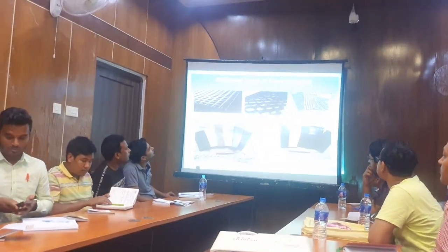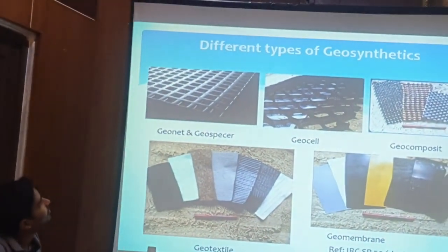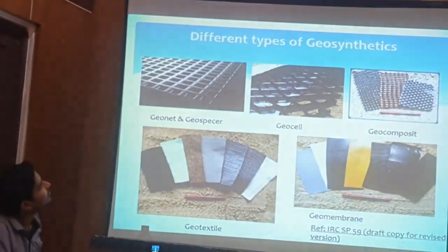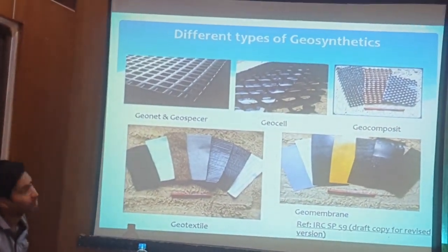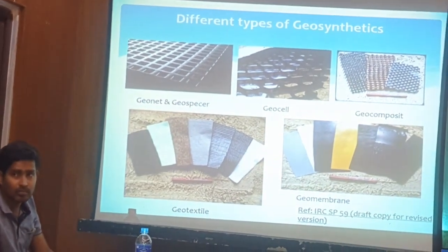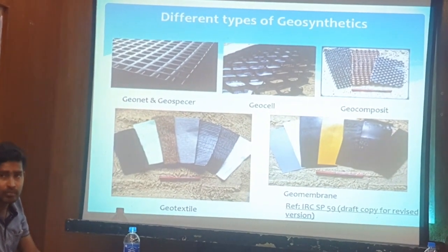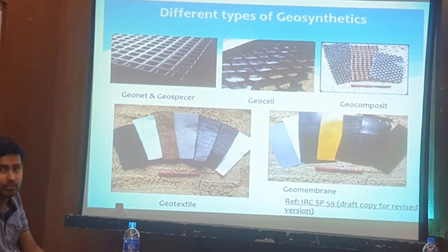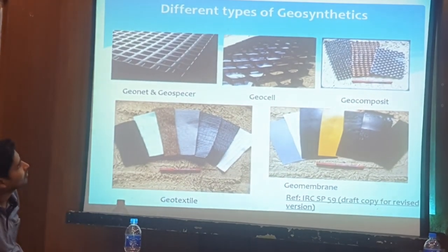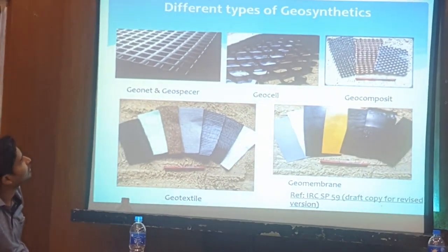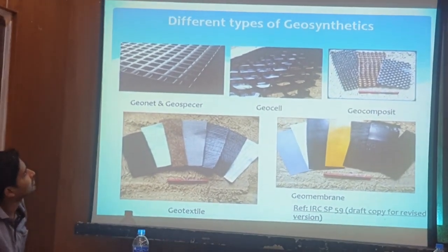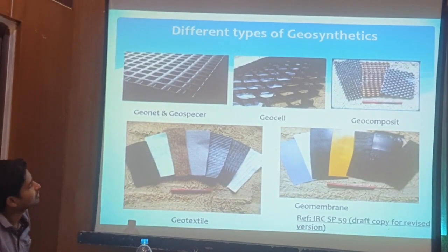Very versatile material which is still much unexplored. That is geosynthetics. So far as the retaining wall and some artwork is concerned, we have used this, but we haven't used this material that much in our pavements. But it is as useful in pavement also. So the code is there, IRC SP 59, 2019 version.